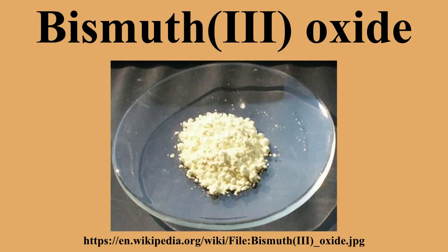The conductivity in the beta, gamma and delta phases is predominantly ionic, with oxide ions being the main charge carrier. Of these, delta bismuth trioxide has the highest reported conductivity. At 750 degrees Celsius, the conductivity of delta bismuth trioxide is typically about 1 S cm^-1, about 3 orders of magnitude greater than the intermediate phases and 4 orders greater than the monoclinic phase.